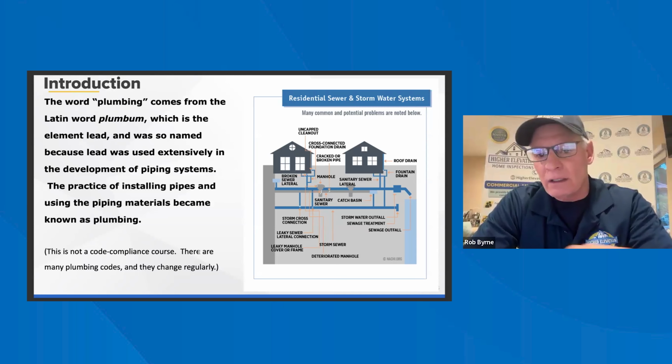So you would explain to your clients that in the summertime, the boiler is going to kick on to give you hot water in the house for your faucets and sinks, domestic hot water. And then obviously the one we looked at before was on demand. And again, on these inspections, you look for corrosion, you see if there's any leaking, that kind of stuff. And a lot of times you'll see this, if the coil fails, then they'll redirect it to a water heater and they'll close this up.